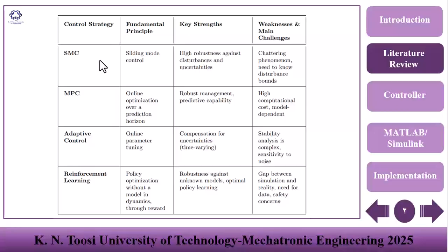More advanced strategies have also been developed. Sliding mode control, or SMC, is very robust against disturbances and uncertainties, but it suffers from the chattering problem, which can damage actuators, and it requires knowledge of disturbance bounds.